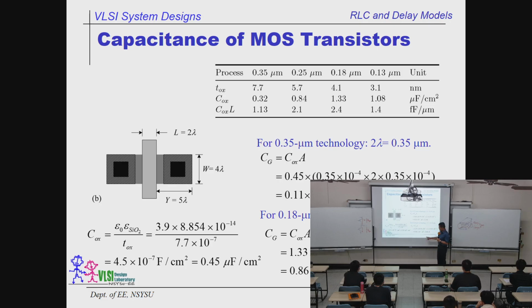It's about 1 femtofarad, 0.86, you use 1 femtofarad. So minimal size, minimal W, minimal L. For the 0.18, for the single unit, you can assume that's 1 femtofarad. Or 0.86, you want to remember that's fine as well. Okay? So right now,